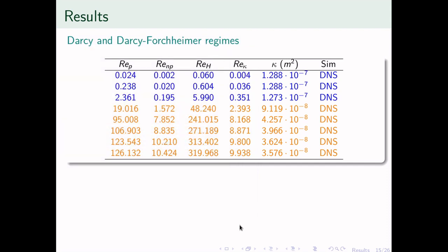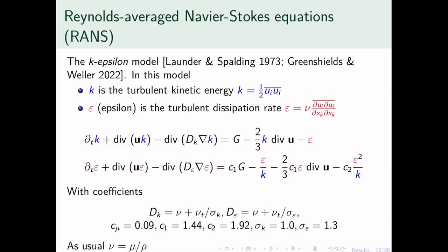At this point, the simulations were no longer stable. The Courant number started to become too high, and we're using a simple computing system. Each simulation was taking around 1 hour to 1 hour and a half. It was no longer stable under direct numerical simulation, so we started to use Reynolds averaging.